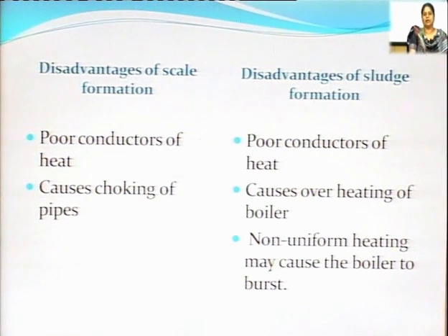Overheating of the boiler also occurs because scale is a poor conductor of heat. In order to get a continuous supply of steam, we have to heat further, which results in overheating, and as such the boiler may even burst.